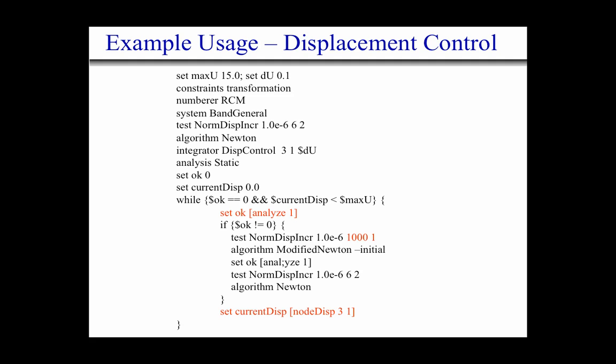You see this little 1 at the end of the convergence test? That tells OpenSees, at every convergence step, print out the criteria and the current norm. While it'll mean a lot of output going to your screen, you'll also see that if I'd given it 2,000 iterations, it might have converged, because I'm converging but not there yet.